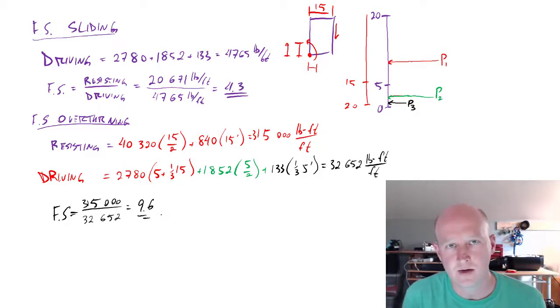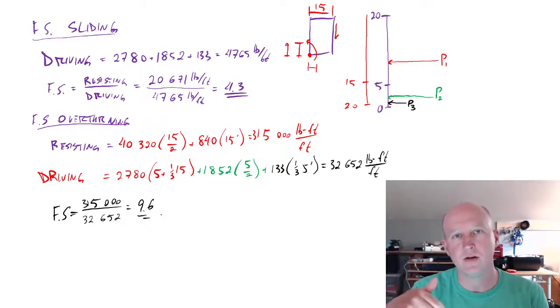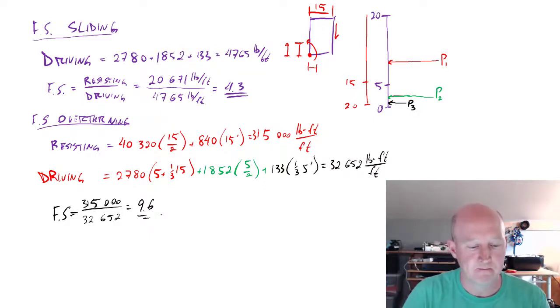So what are their moment arms? What are the directions that they're working? Keeping in mind that the vertical component of the driving force is actually a resisting moment. And you need to include that in calculating your friction component of force along the base of the wall. So we'll continue from here to do a few more examples, and then we'll look at a few different types of retaining walls and learn things about mechanically stabilized and sheet pile walls.